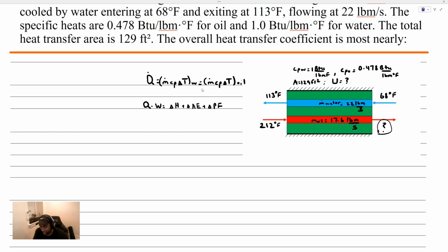What we can note is that if we take our system to be the entire heat exchanger here, no heat transfer is going to occur outside of the system. There'll be no heat crossing the boundary of this system because everything's happening internally. So the heat transfer is going to be zero. There's only internal heat transfer. There is no boundary work or other forms of work mentioned in the problem. There's no speeds or height changes, so the kinetic and potential energy changes drop out.